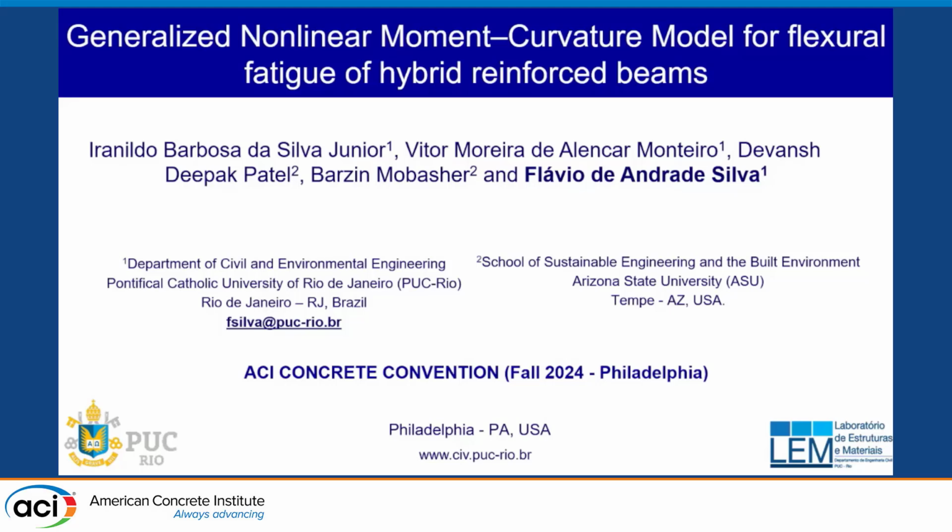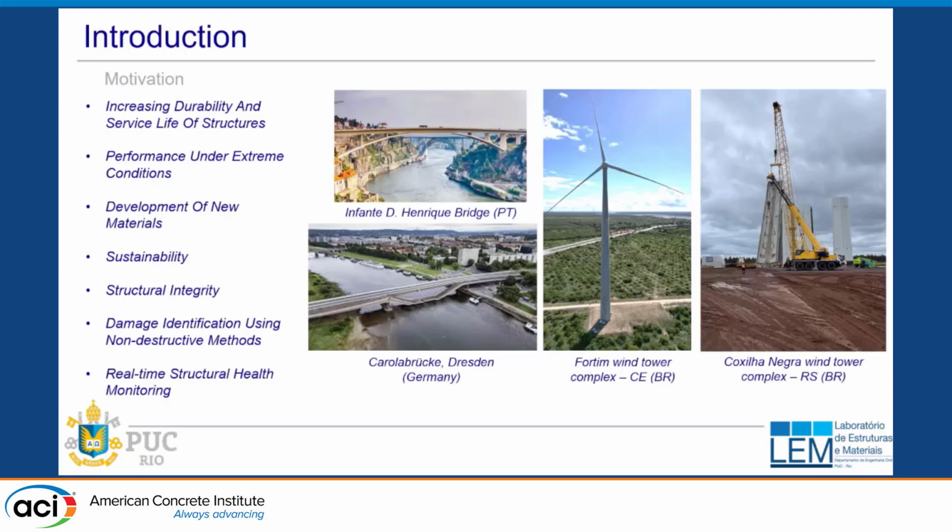And the idea here is to run fatigue tests, but try to develop a model that would allow you to characterize not only fatigue performance of concrete in a flexural mode, but also do it on a reinforced concrete. What is the fatigue performance of a reinforced concrete that has fibers in there, and it receives contributions from basically both the steel rebar as well as the concrete phase.